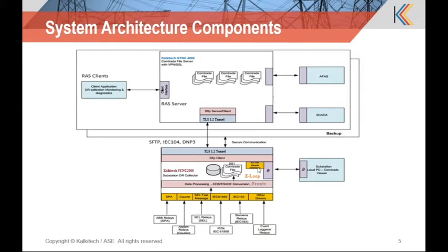All these files, Comtrade files, loop impedance files and event files, can be pushed to multiple locations depending upon how you configure. So there can be a main center as well as a backup center available in the network, and there can be a local substation Comtrade viewer or analyzer, and that can even be pushed to the local machine for analysis and viewing purposes.